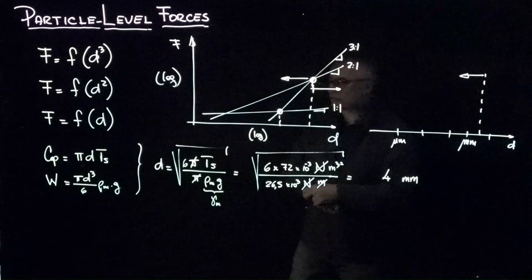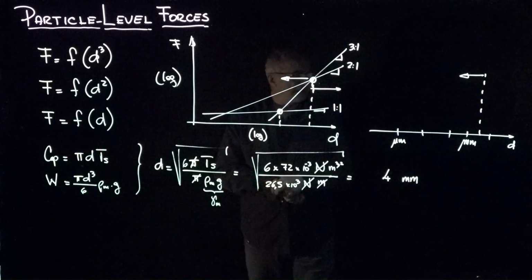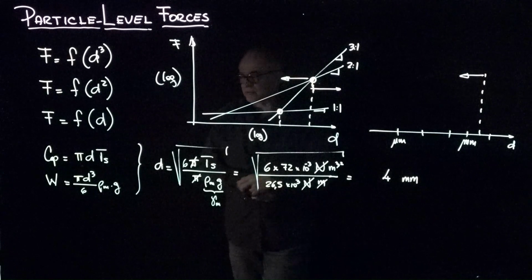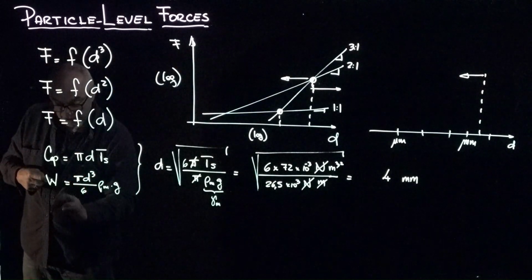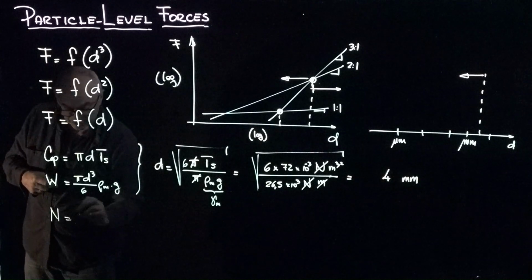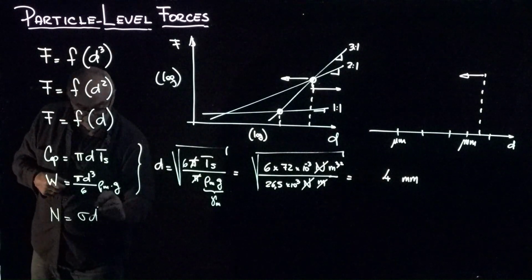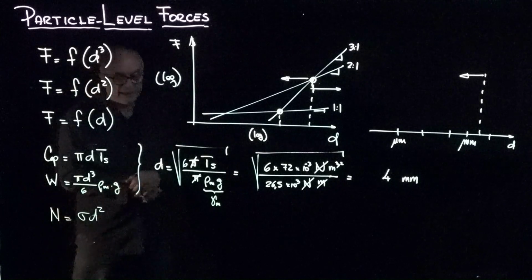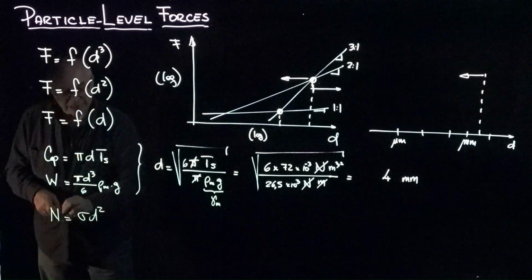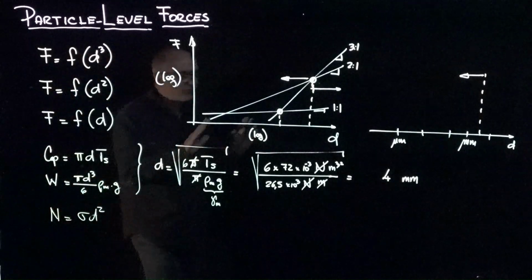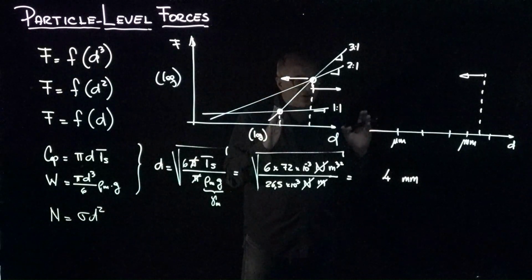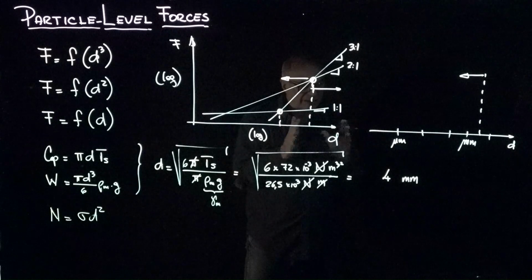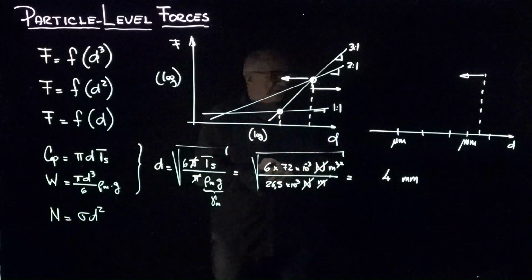Now we can do similar analysis to identify other boundaries. For example, when does the skeletal force, the normal force N, which you may remember was sigma d squared, prevail? And then we can compare what about the electrical forces. The electrical forces get a little bit trickier because there is this dimension of the interparticle separation that we need to take into consideration.